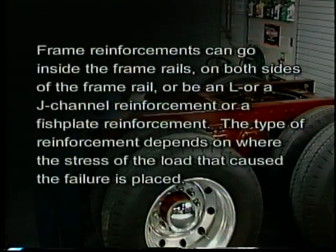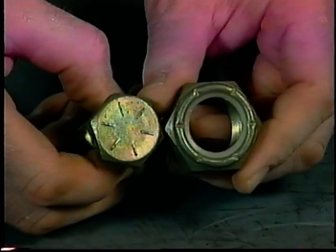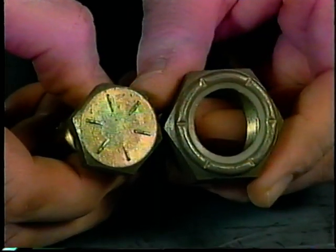Frame reinforcements can go inside the frame rails on both sides of the frame rail, or be an L or a J channel reinforcement, or a fish plate reinforcement. The type of reinforcement depends on where the stress of the load that caused the failure is placed. Fish plate reinforcements can be bolted to the outside of the frame with SAE grade 8 bolts and nuts placed in a rectangular pattern to strengthen the frame. The reinforcement may extend below the frame. Bolts are the preferred fasteners for frame reinforcements.